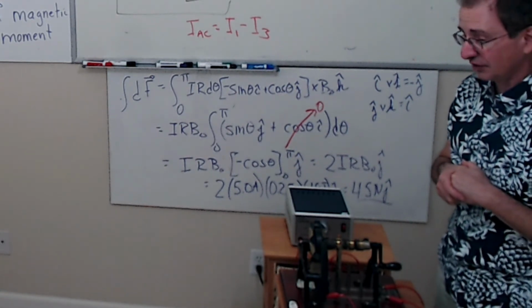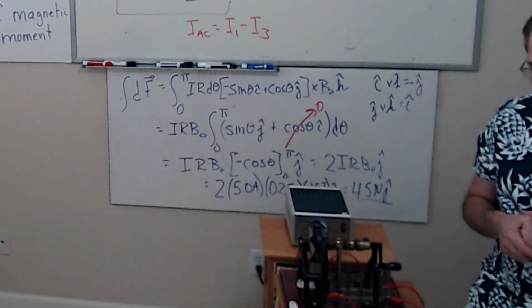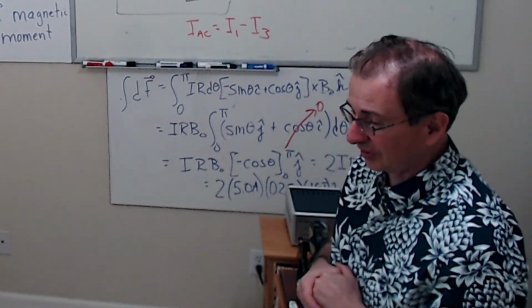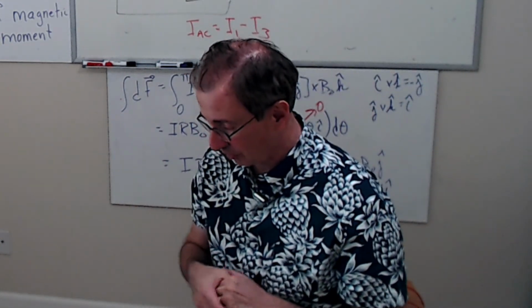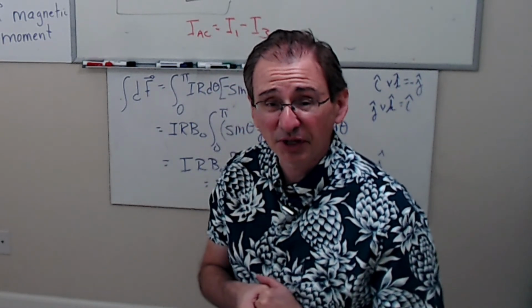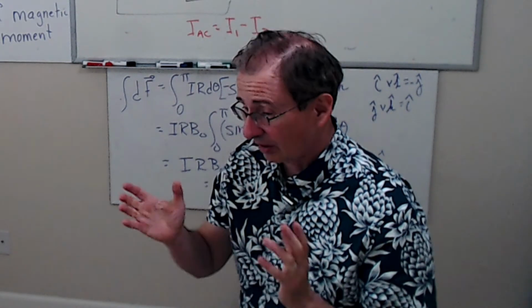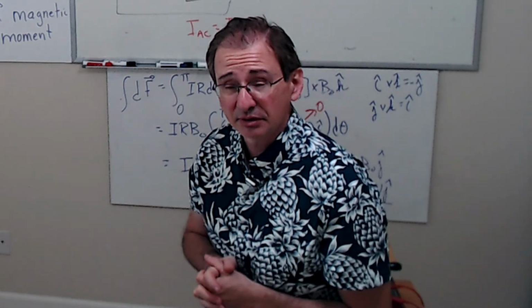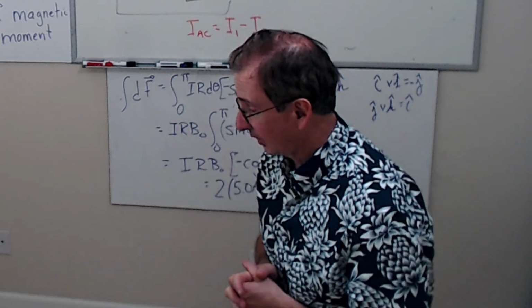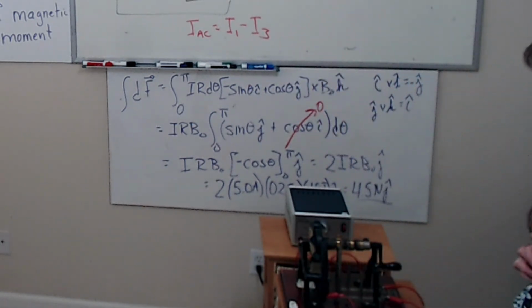If you don't run things in series, your batteries will go down real quick. You'll actually be running so much current in your motor that you might melt the coating. That wire is coated. You melt the coating, then you mess up your motor. So you're going to have to hook up everything in series when you do that. Okay?